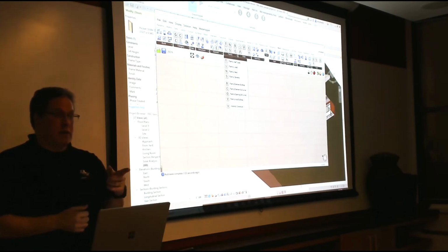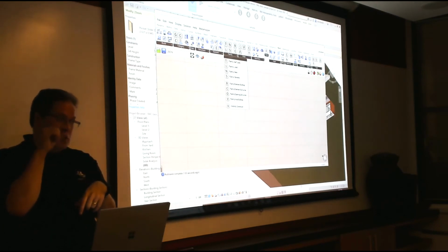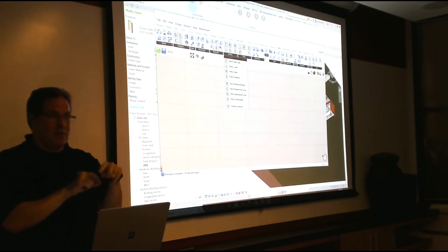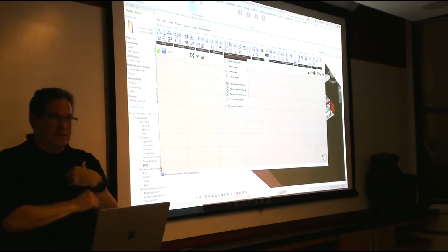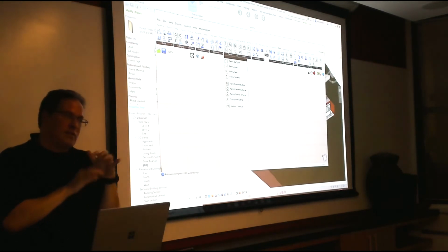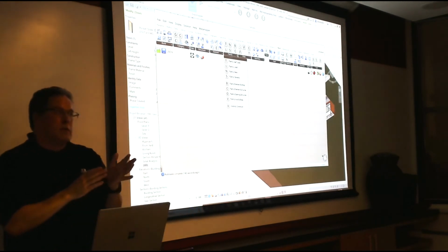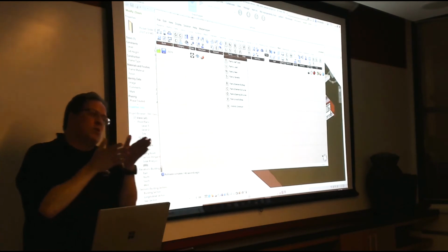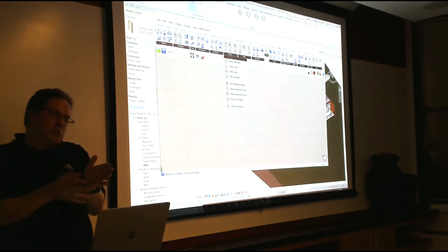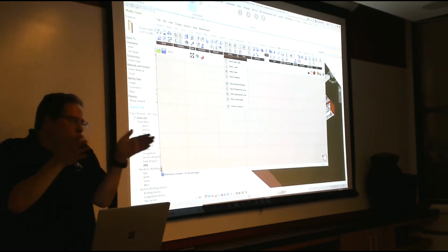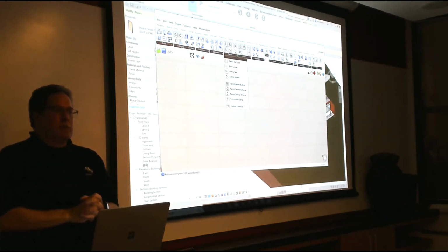So we talked about having SubDs. We have SubD walls pushing with windows in them in Revit, but because Rhino's sitting there, it gets very "it depends." It depends is what it comes down to. So you can use Revit's tools, or you can override everything by getting Rhino to do it and just popping it in the families. And there's a lot of gray area in between them. In our daily flows, there was going to be rationalization anyway in Rhino first, because we need to dimension the radius and stuff like that.